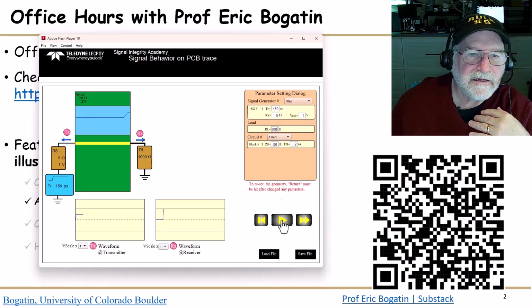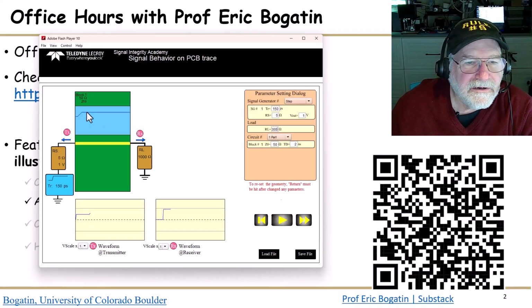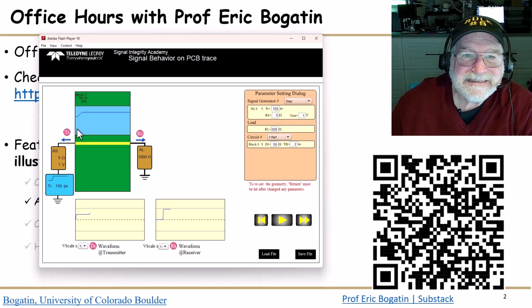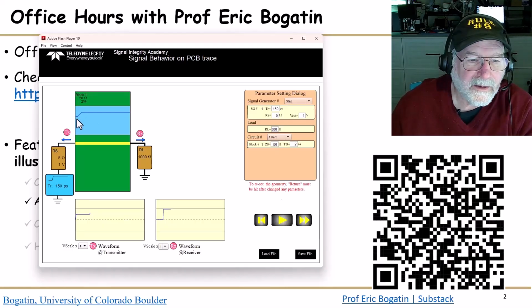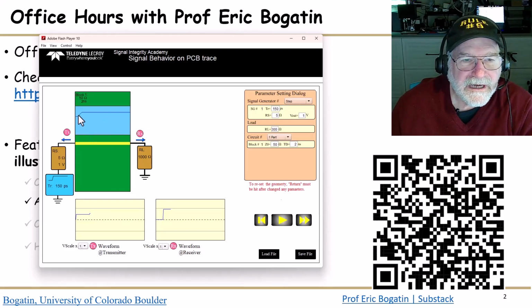So let's watch that. Here's that positive 1 volt propagating. It's going to hit that negative voltage, and there it is. And look, here's that voltage that was going in, the 1 volt. It changes sign and then reflects. And so the voltage that we see here is that initial voltage minus the reflected voltage because it's got the opposite sign. And now it's going to continue propagating down the line, and we're going to watch that negative going voltage propagate down the line.